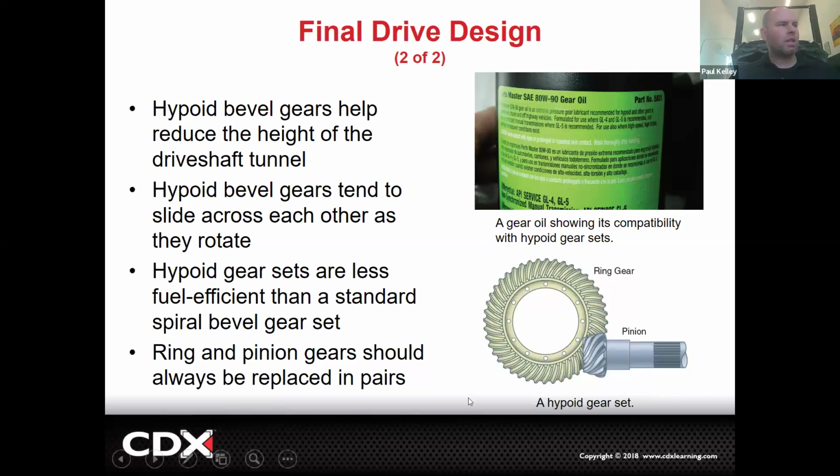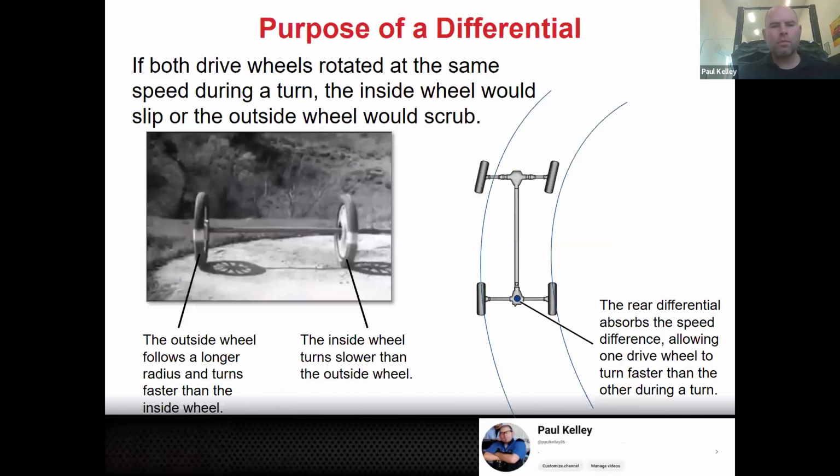And they did have, like I was saying, spiral bevel gears, but a spiral bevel gear would be if this pinion was on the center line, and that's why hypoid is just a bit different. Cool. And then again, we talked about this differential. If this was spinning, you know that this would be going slow and this would be going fast, and this one would be kind of skipping and slipping and hopping across the ground. So that is kind of a summary of what we talked about.